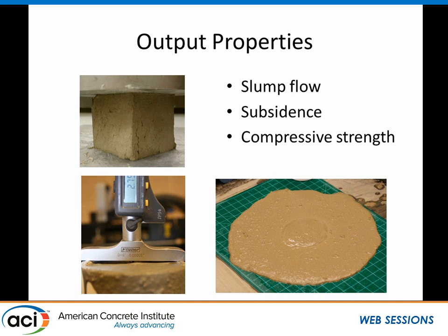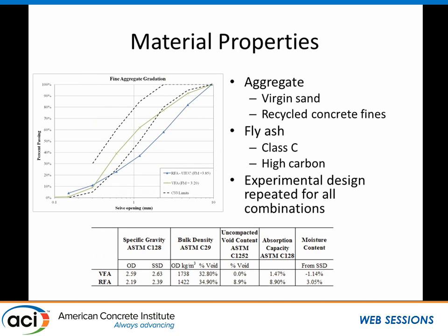And so we're thinking about the slump flow and the subsidence, that would be the loss of volume over some time. And then, of course, we do keep an eye on compressive strength, but we're trying to target these low strengths. So there's a couple pictures of how we do that with cubes, cube compressive strength, and subsidence is a volume change measurement, and then there's the slump flow picture.